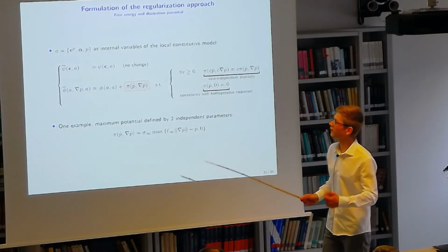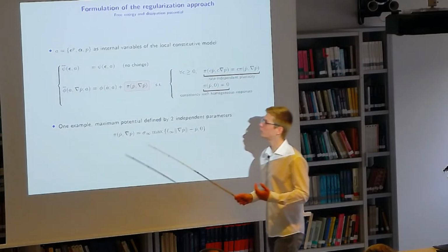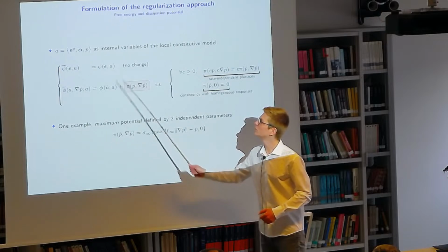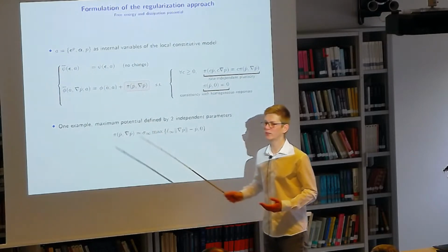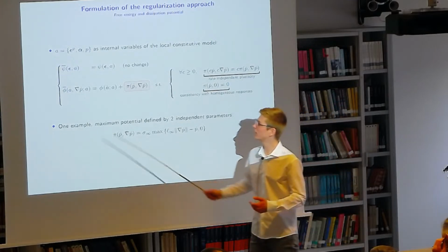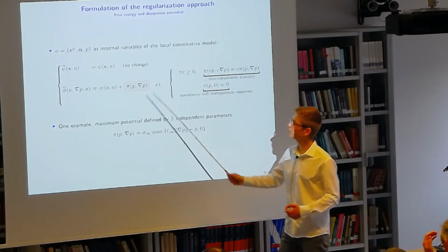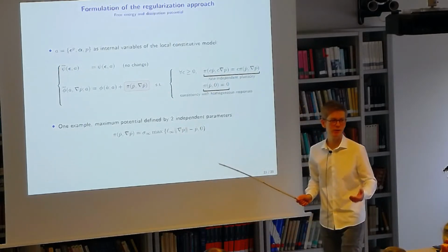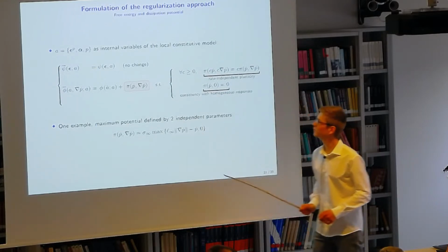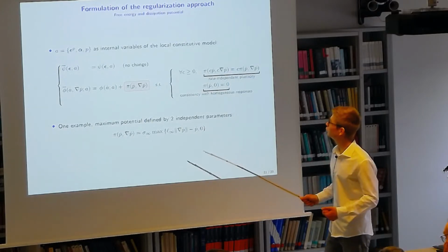In order to define a model with gradient of plasticity, we take, for the expression of the free energy psi bar, the same expression as for the local one, which means that there is no involvement of the gradient of plastic strain. Next, the dissipation potential phi bar adds next to the local part a new contribution in a function pi, which in general takes as arguments both the rate of the cumulative plastic strain and its gradient.